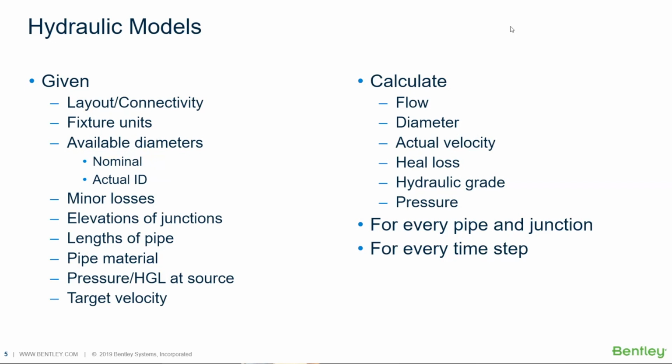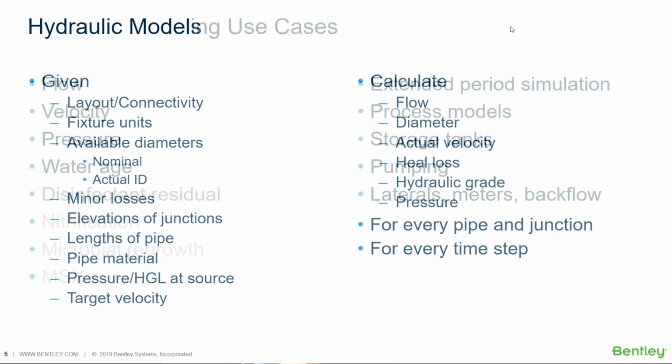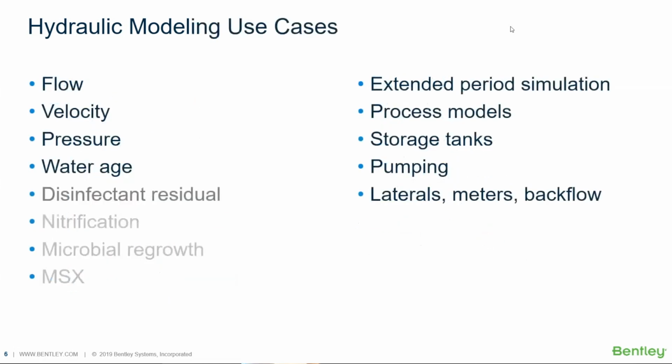And so this is where we're advancing as far as hydraulic modeling, what you put in and what you get out of a hydraulic model. And there's a lot of use cases. The most important ones we can do very easily right out of the box right now are flow, velocity, pressure, water age, and things of that sort. And with the right coefficients, you could do disinfection decay.